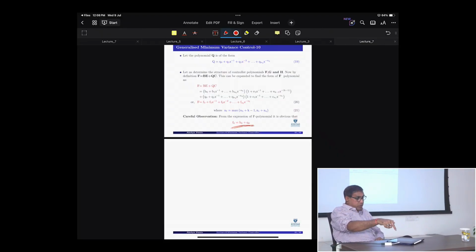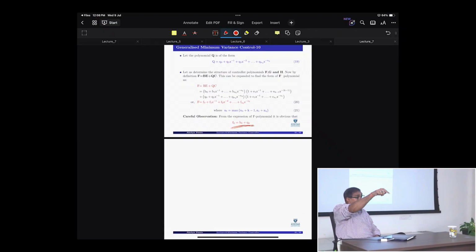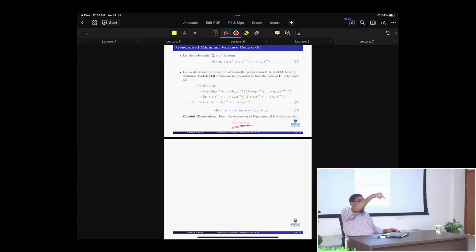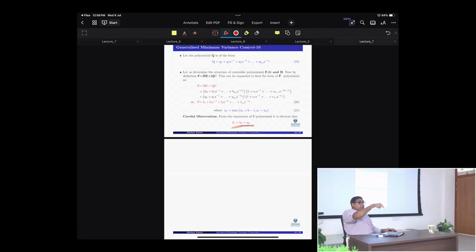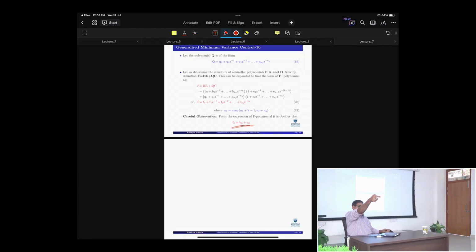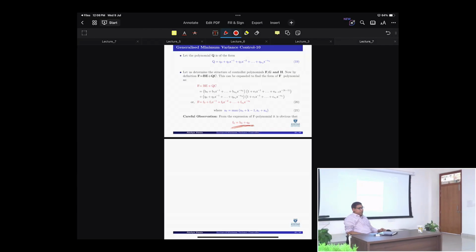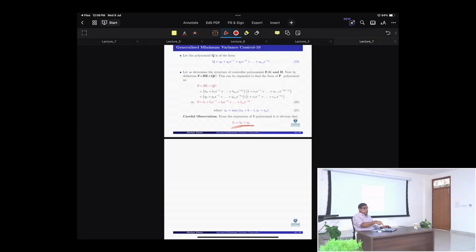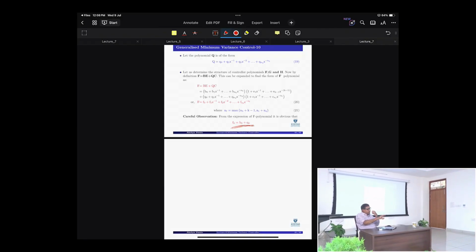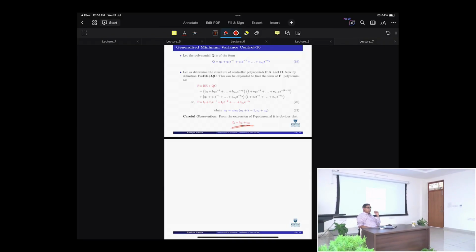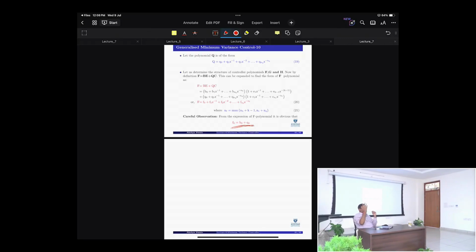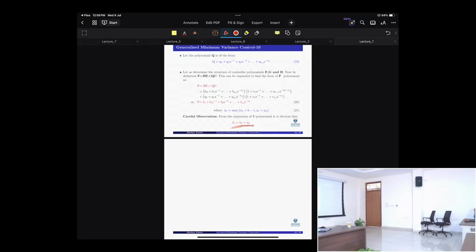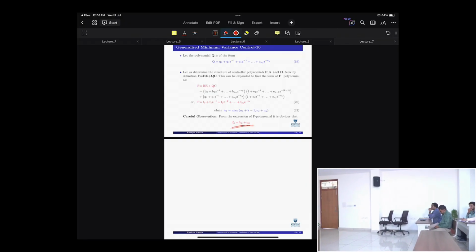This one is also a sort of predictive controller, because you are doing y t plus k, you predict it. You are not minimizing the variance of the output, you are minimizing the variance of the predicted output. Okay, this is also predictive control. David Clarke developed GPC based on this, a different type of model but a similar type of model, with a similar control horizon and all these things. But I am telling you, MPC, our students are doing it because now we have to publish papers.